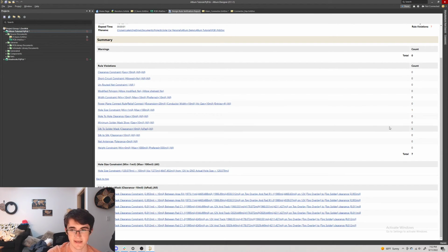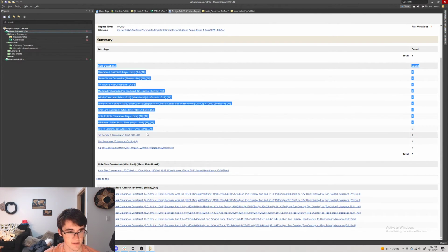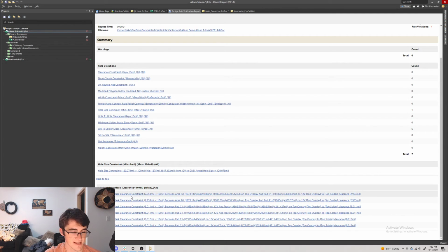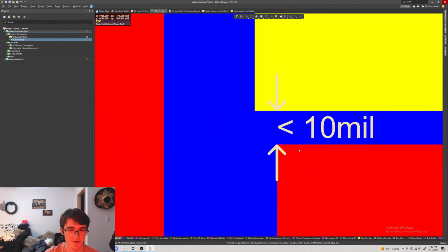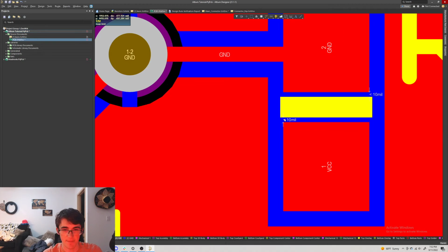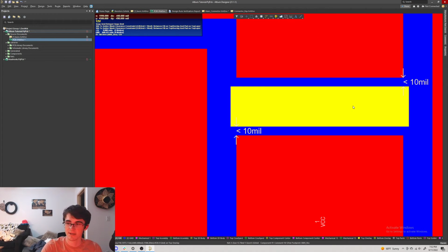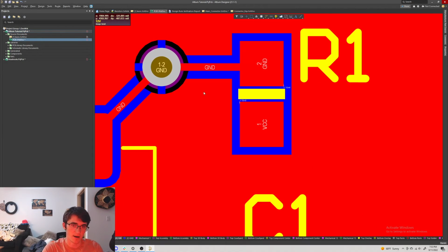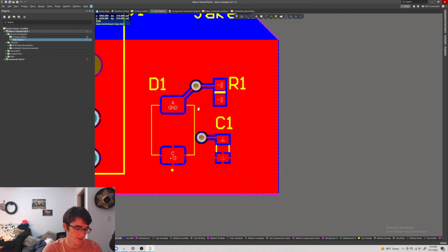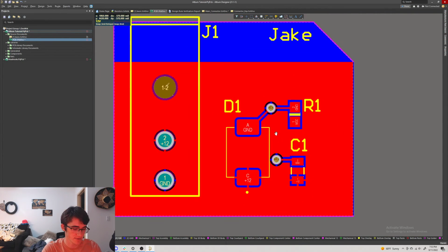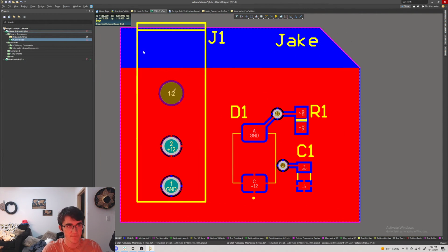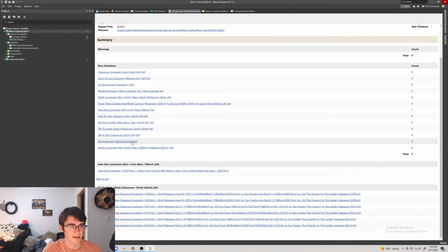But then you also can see there's 6 more issues with the silk to solder mask. This just has to do with where the silk screen is and how close the gap is between the silk screen layer and the actual copper trace layer. This is another Altium default. Normally, it's not an issue with different manufacturers like JLC PCB or other places. So I've never really had issues with it. But yeah, so now you can say, cool, our DRC is good.